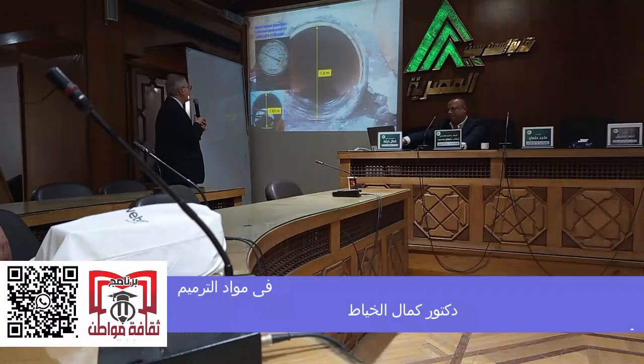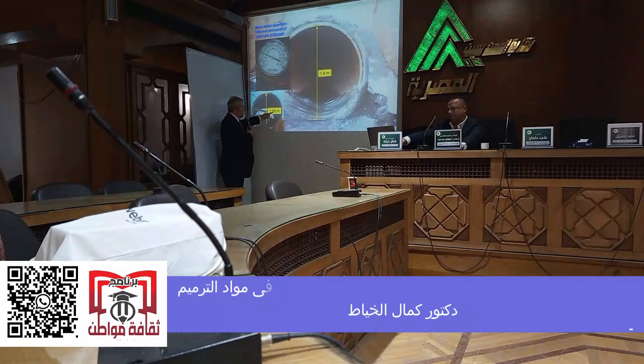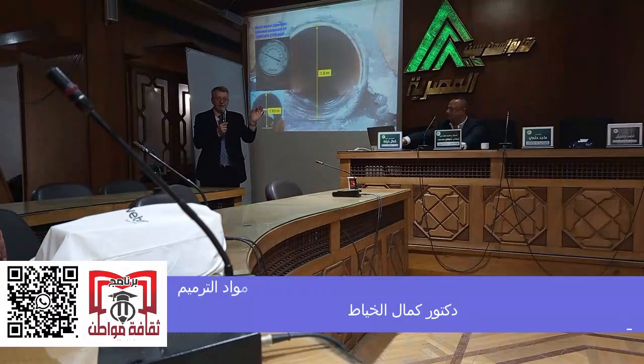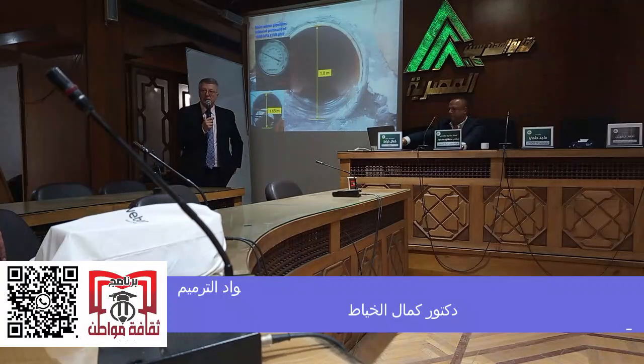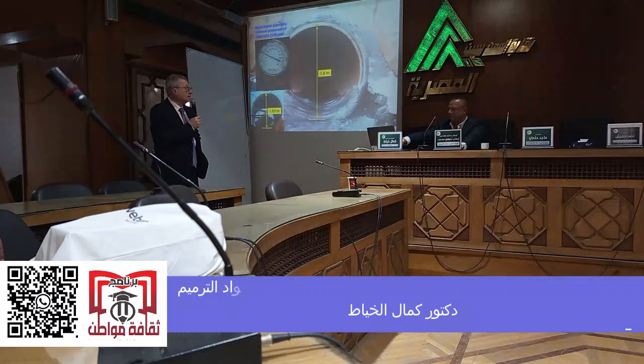So you have the diameter of 1.8 meter, and you have the corrugated steel, if that's what it is, or other types of materials that are smaller in diameter. So the difference between them divided by 2 is the space that you have to penetrate. So that's about 7.5 centimeter on average on each side.